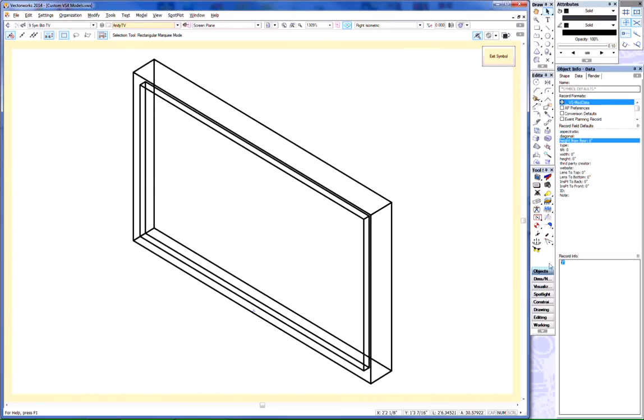I'm going to come down here, and I know that screen wants to be an inch off the insertion point, so that's the height off the floor. Type must be TV. If it doesn't say TV, you're going to get errors. We're not going to tilt the screen back at all. The width here, I know that I want it to be 32 inches. I could measure that if I wanted to, but I just know going in that's what I want. And I know I want it to be 18 inches tall. Third-party creator and website is where I could put my name and my website. So if I was to share this symbol with anybody else, anytime they used it, they would see my information in the OIP.